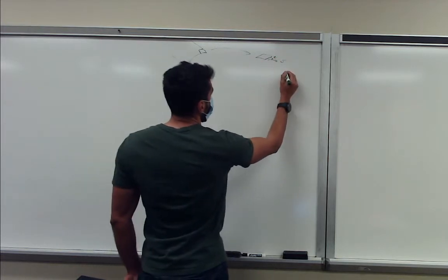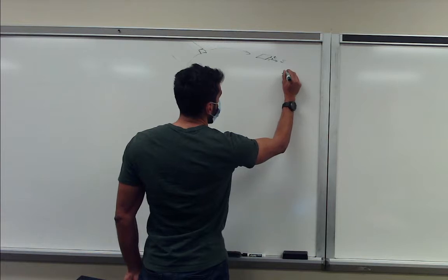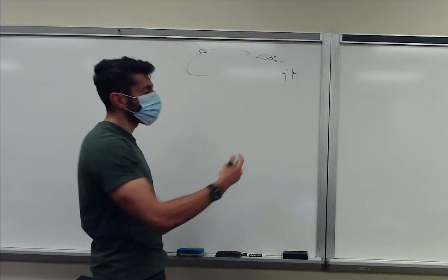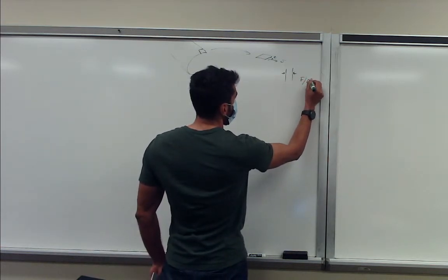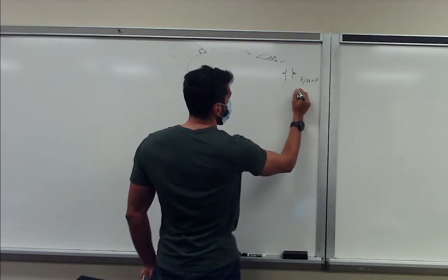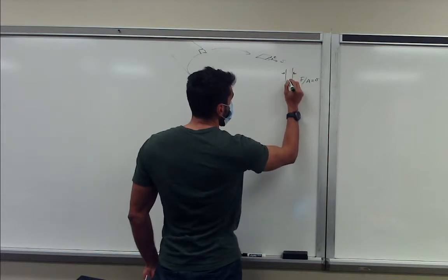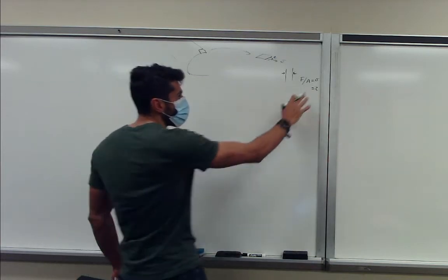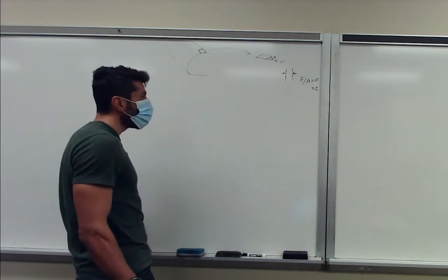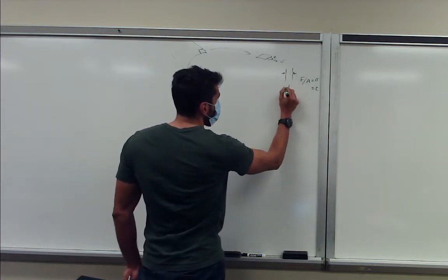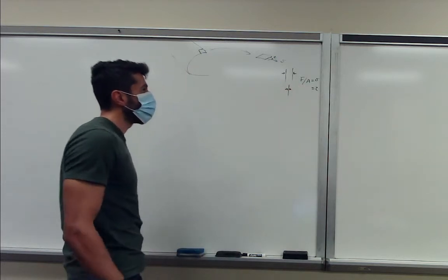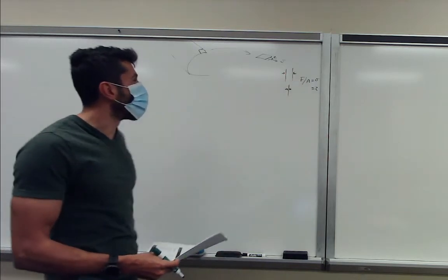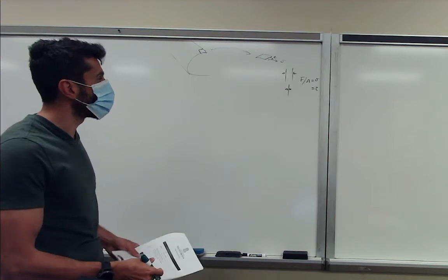We said, well, if you have a thick wall structure, then the variation in thickness is basically constant. And since we always go from forces to stresses, we can always divide a force over an area to get a stress. If we're looking at the in-plane stresses, then we can get a sigma and a tau, the shear stresses, out of it. But if we go to a thin wall structure, we always said we can ignore the thickness, and then this upper part would be more difficult to understand and do.